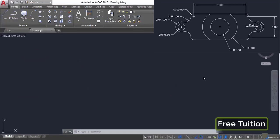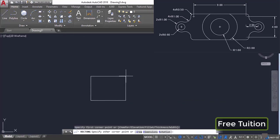So I'll start this geometry using a rectangle tool. So I'll go to the draw panel, select the flyout and select this rectangle tool. Now click anywhere in the drawing area and then I'll make the rectangle. For making the rectangle, I'll type add and then the length of the rectangle, which is 10.